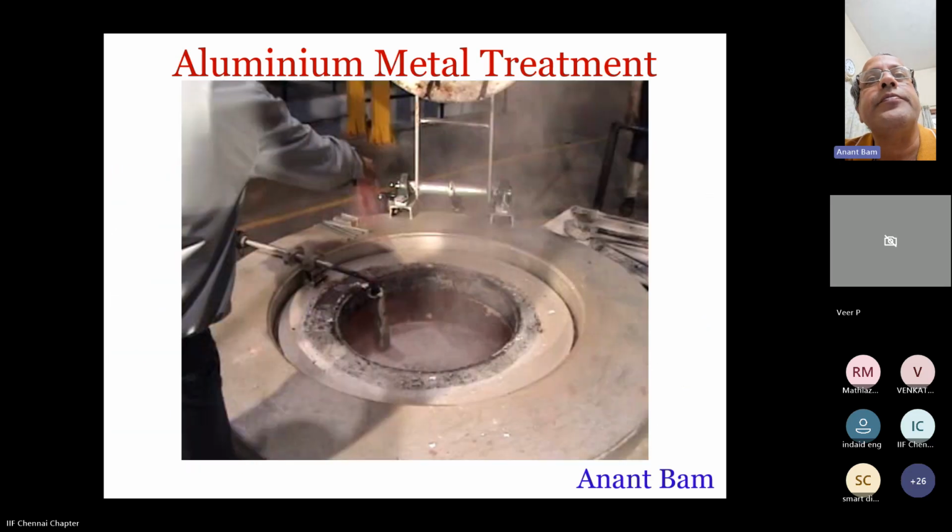Next, please. Okay, this was also a video which unfortunately is not playable in this case. A person is putting some cover flux or coverall flux into the crucible and then churning it, then separating the dross. Next, please.